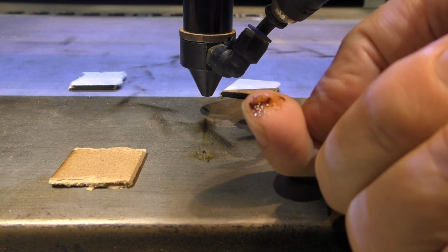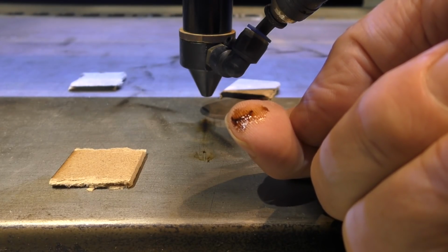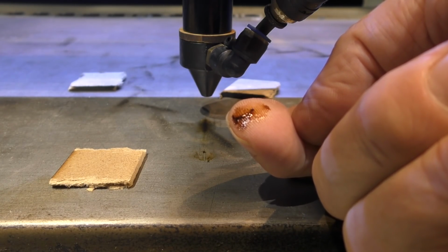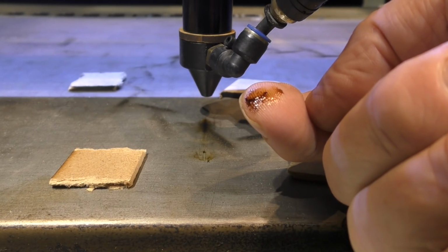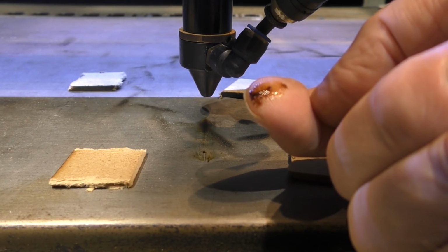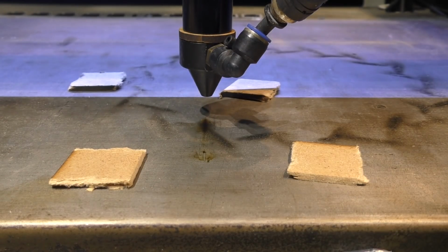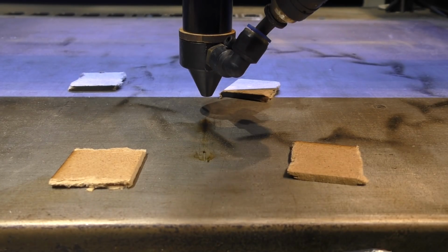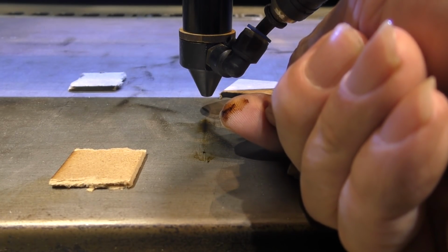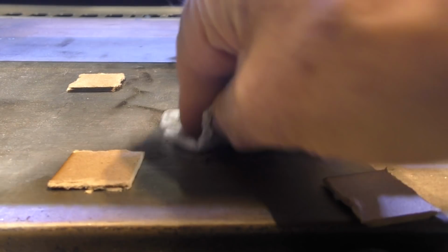That's what would normally go onto the surface of your work. That's the tar that's being generated in those fumes that I talk about. That's the liquid content of that white smoke. I've just condensed it onto this very cold surface. So if you've got any doubt as to what that brown stuff is on the surface of your material, it's not burning. It's recondensed tar. I'll just clean it off with a little teeny weeny bit of acetone.